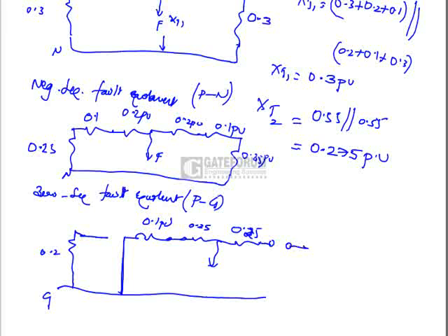After that we have delta connection, so this is grounded. After that we have star connection. Okay, this is isolated one which is having a reactance of 0.2 per unit. Okay, now this one is 0.1 per unit. Now what is the fault equivalent? We have to calculate between these 2 points.